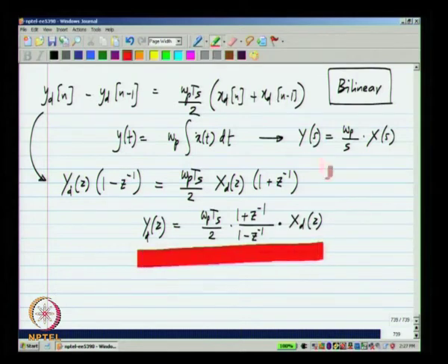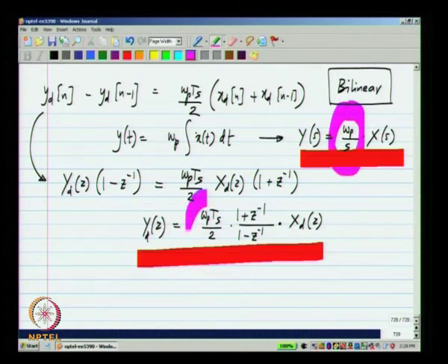So, this is an approximate realization of that, okay, where yd represents the samples of y and xd represents the samples of x. Okay. So, to transform a filter from continuous time to discrete time, the continuous time filter will be described in terms of s as polynomials in s. So, what we have to do is substitute this part with that. Okay. Then basically what we are doing is each integrator in the filter is approximated by its discrete time counterpart. So, the overall filter will be a reasonable approximation to the original continuous time filter you started off with. Okay. That is the idea.